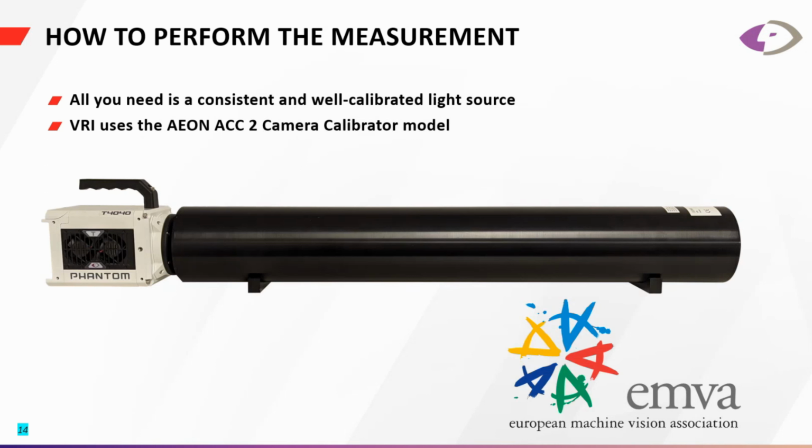It uses 3 different LEDs for the test: a blue LED with a center wavelength at 466 nanometers, a green LED with a center wavelength of 532 nanometers, and a red LED with a center wavelength of 629 nanometers, all of which can be current controlled to adjust the brightness for the different measurements from dark to saturation. It also has an F-mount connector for easy camera connection, and it's about 90 centimeters long, 13 centimeters wide, and 14 centimeters high if you're interested in that.